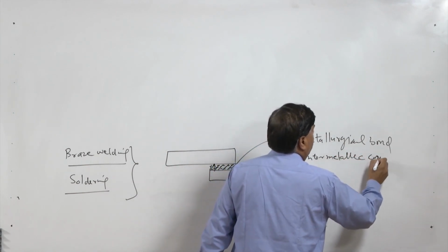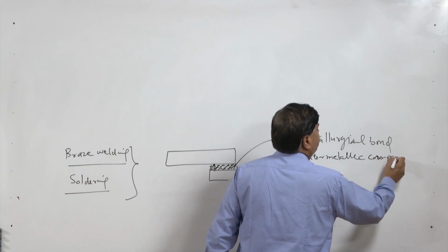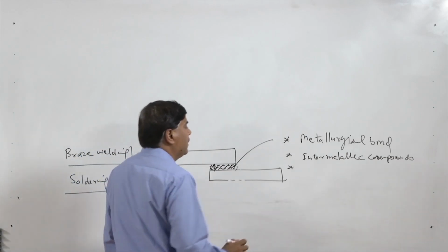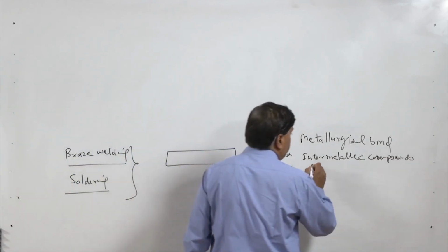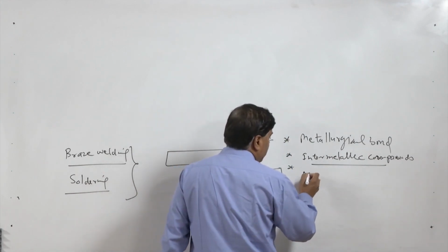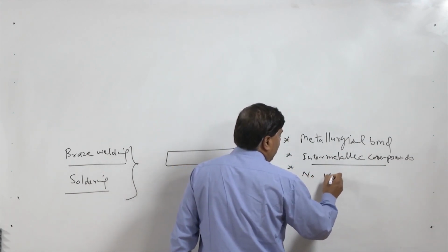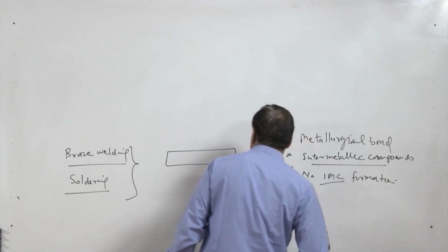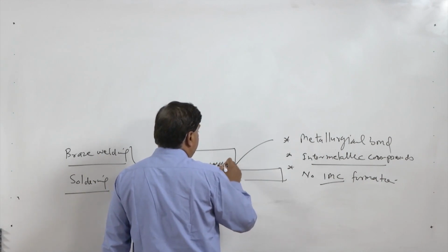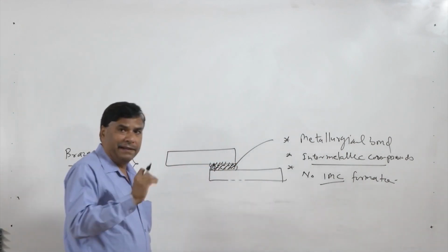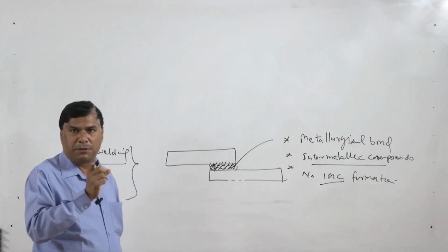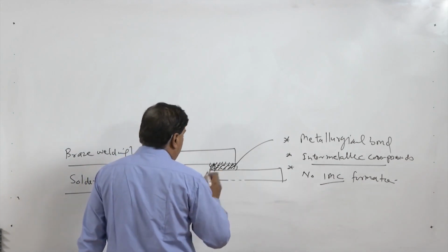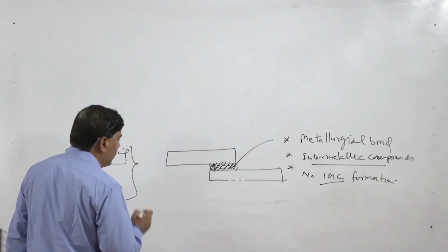between the sheets. If there is no intermetallic compound formation, then the strength of the joint is solely governed by adhesion, the way by which the solder metal interacts and closes the gaps at the surface of the workpiece or the sheets.